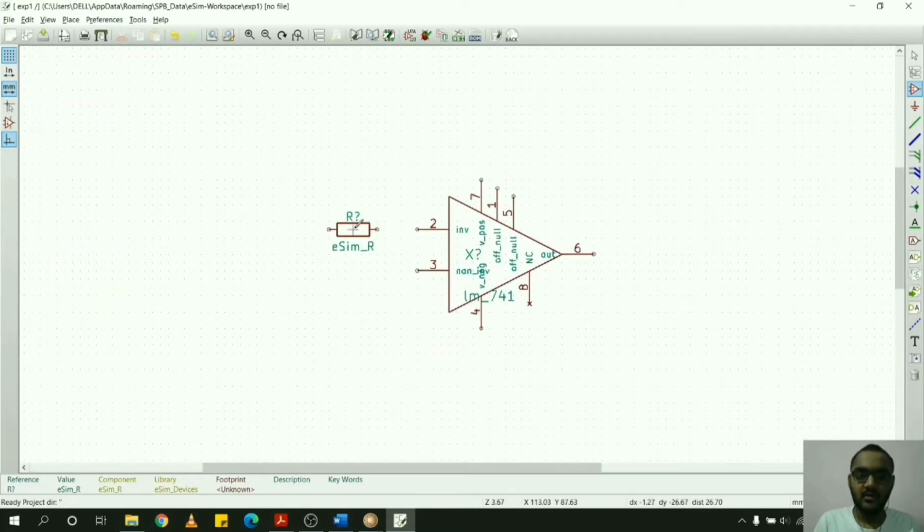Put your cursor on a component and press C to copy the component. Select a component and press R to rotate the component. To join the components using wire, place your cursor on the terminal of a component and press keyboard key W.